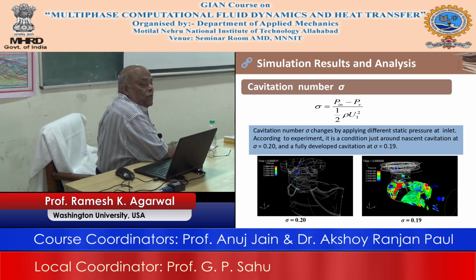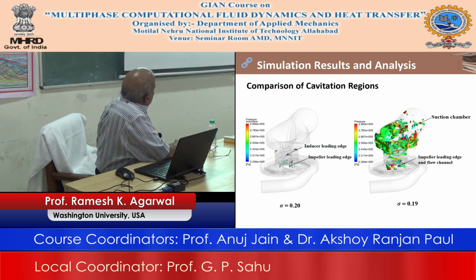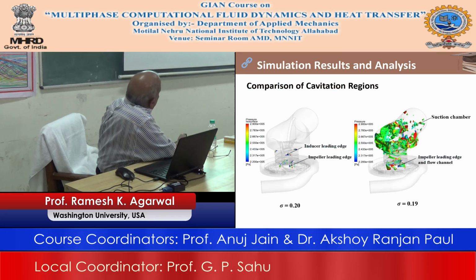This is so sensitive, the way it is defined, because this difference in pressure, a small change in the difference in pressure can make a lot of difference. So if it is higher than this, there is no cavitation, and if it slightly goes down, it approaches the cavitation pressure, that's it. It can have a massive cavitation. So it's a very instructive slide with sigma equal to 0.20, sigma equal to 0.19, and again it shows more details of it on various parts.